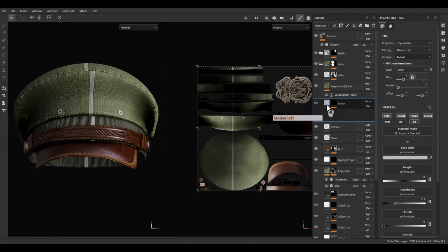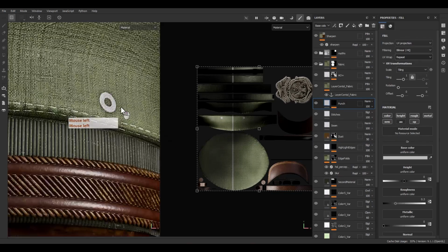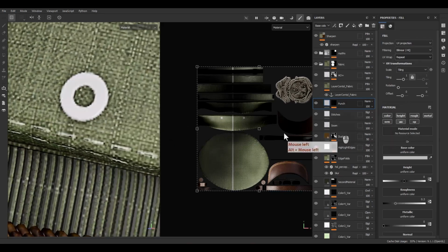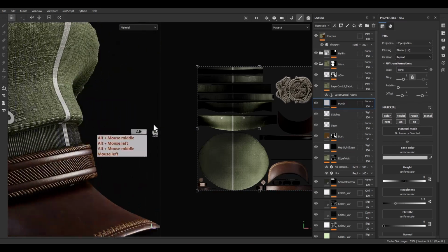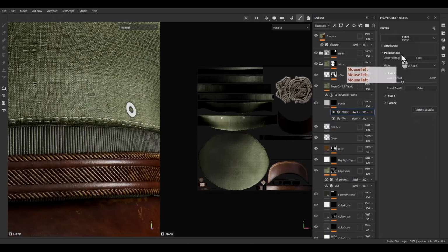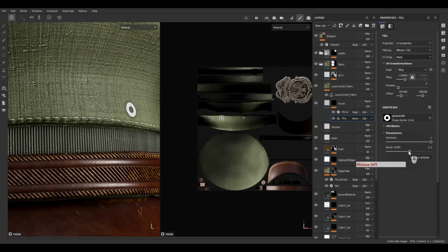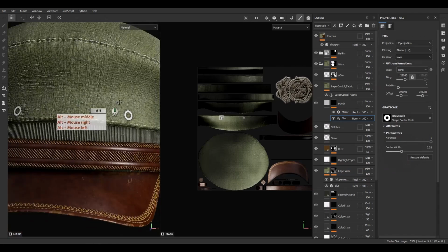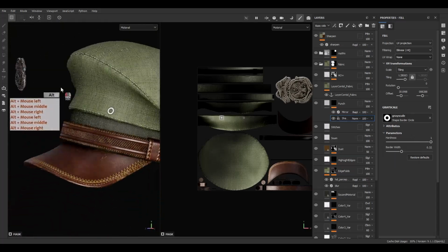Yeah. And let's add the normal in the layer and AO, because in this way, we don't see the data from the down level, okay, down layers actually. So let's play with the parameters to achieve what we want. Let's disable this display debug, and after that, I'm going to adjust this slider to define what I want. Okay, it's okay. Everything is okay.